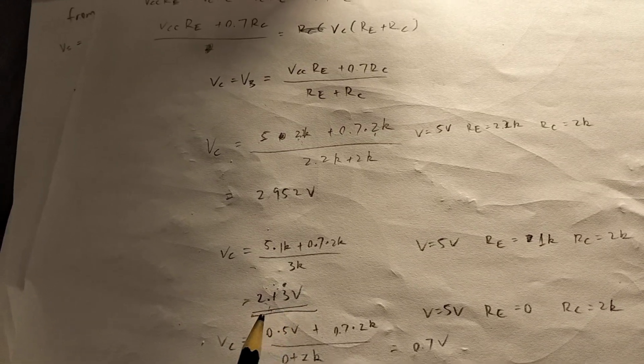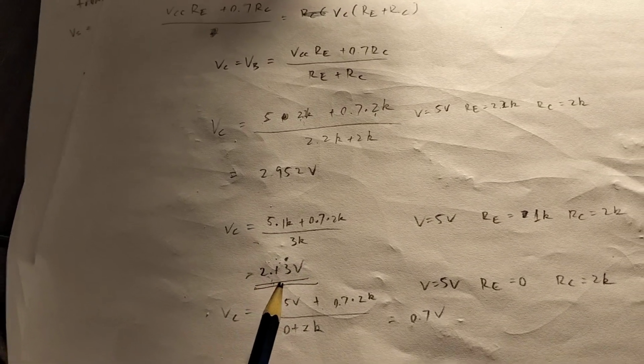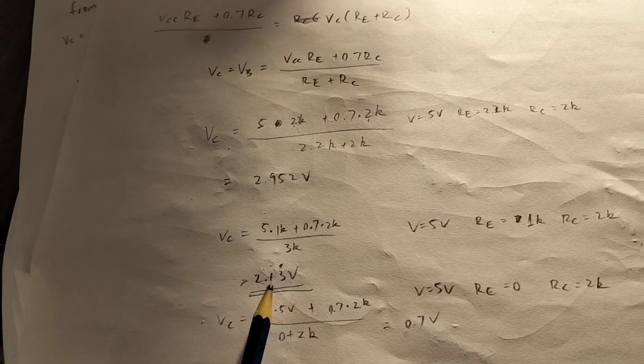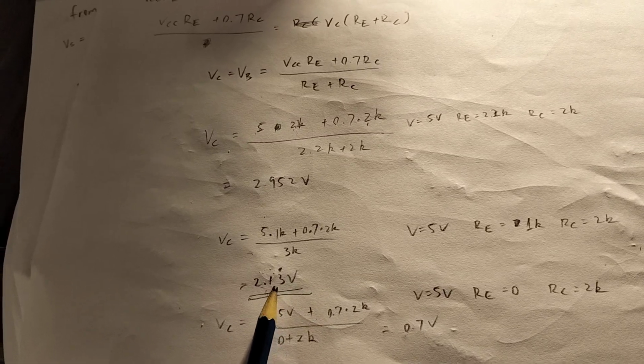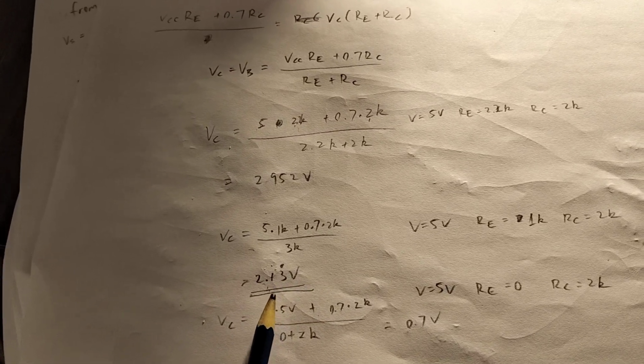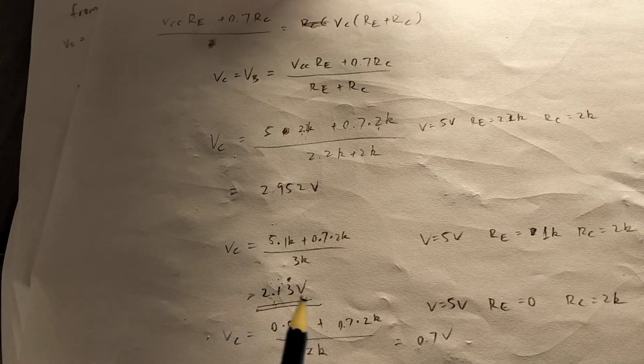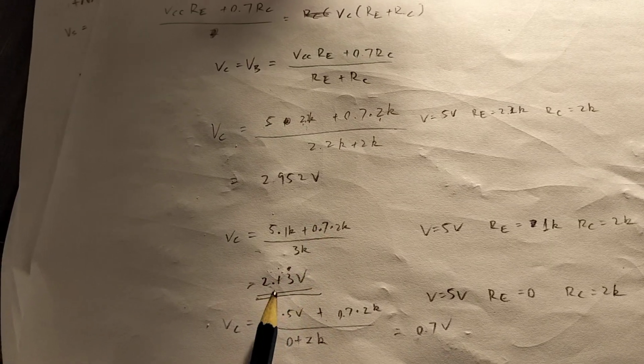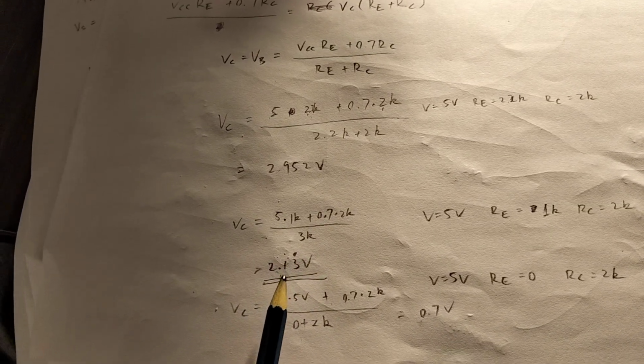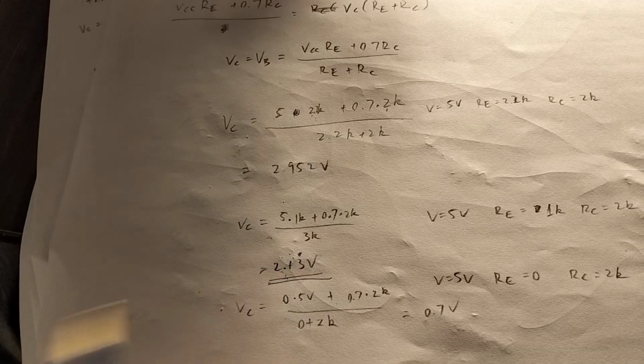But I didn't see that. In fact, they varied quite a bit. So one was at 2.3 and one was at 1.9. Basically 0.2 volts above and below the equilibrium voltage, which makes sense because one of them was close to saturation and one is close to cutoff.